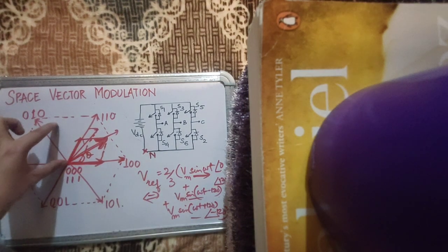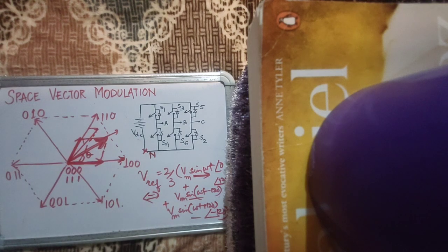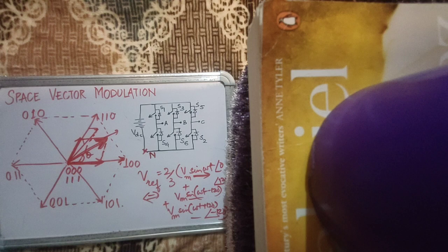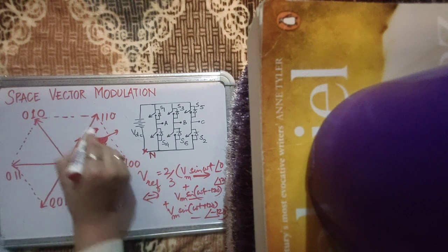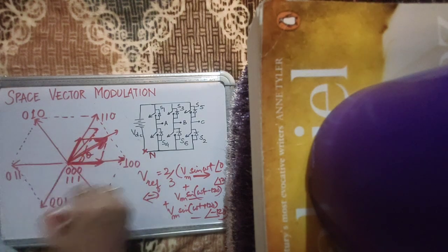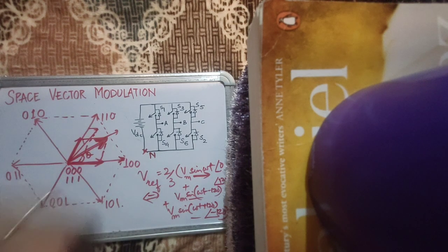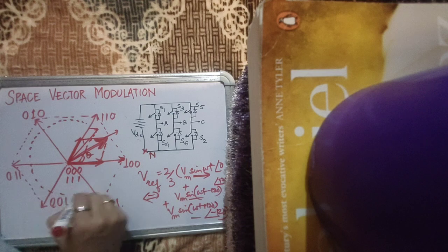And you go on moving around this space vector diagram, continuously going round and round, and continuously you calculate your adjacent vectors, and for how long you have to switch them, such that you create the effect of tracing a circular trajectory, so that you create an effect that you are tracing points in the middle when you don't even have vectors in the middle.